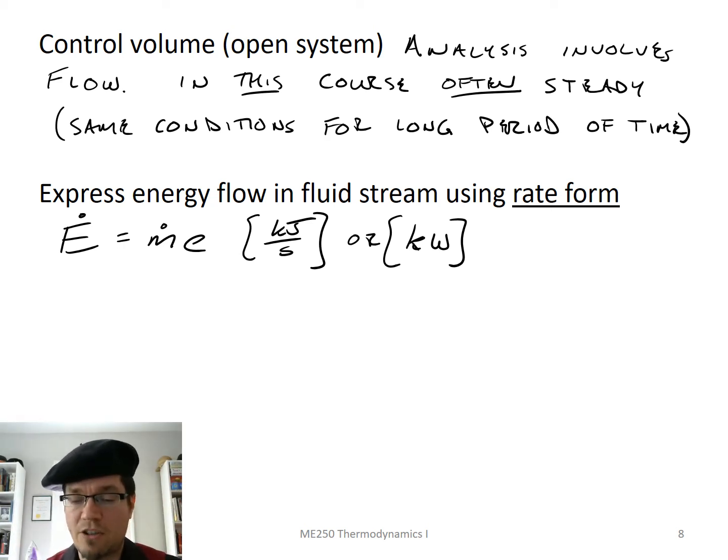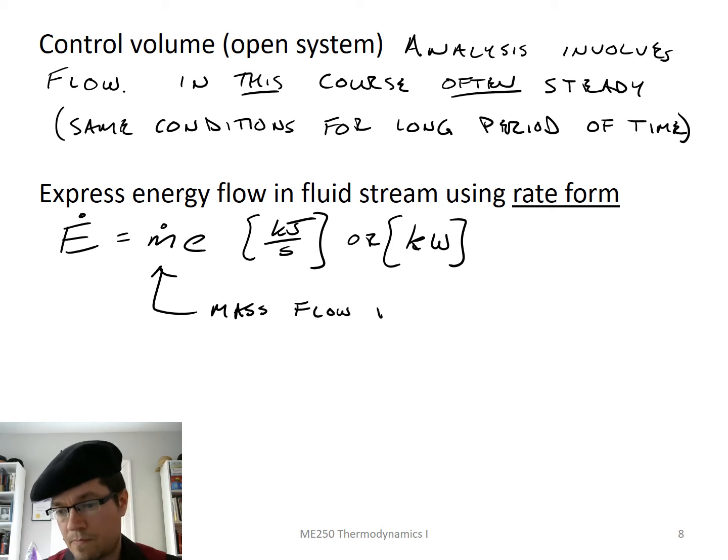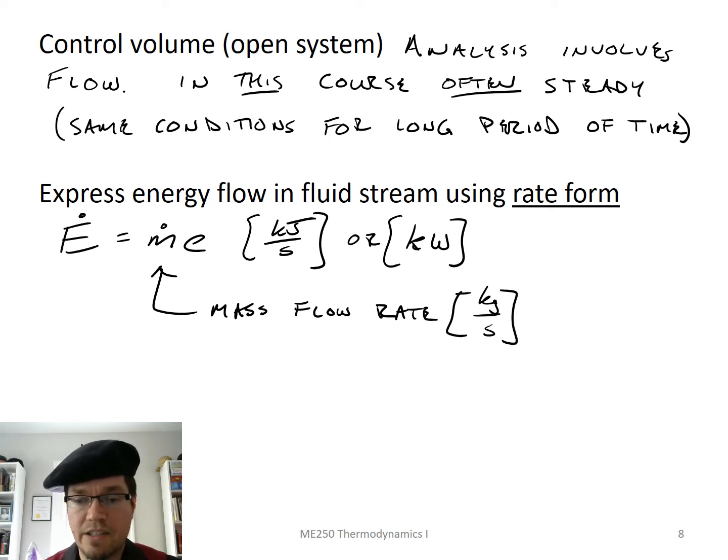Again, we'll cycle back to all of this stuff that we're going over in the introduction, but I want to give you an overview to begin with. So this is the mass flow rate. And it is in mass, SI units of kilograms per time, SI units of seconds. Obviously, you can convert to other things if you need to. And that mass flow rate is very often going to be expressed as a density times a volumetric flow rate, which is very often, again, going to be expressed as a cross-sectional area times some average velocity.